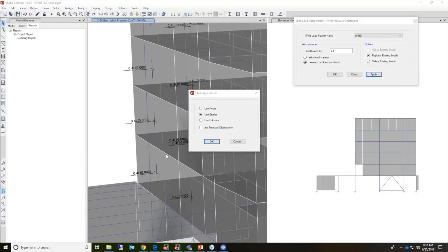Okay, so does ETABS consider the gust factor based on the building's natural frequency, or must the user calculate that separately? Yeah, we do have the capability of the program calculating the gust factor, but that is limited to some of the codes, and those are defined in the user's manual for which codes we actually calculate ourselves. And the program calculates it.